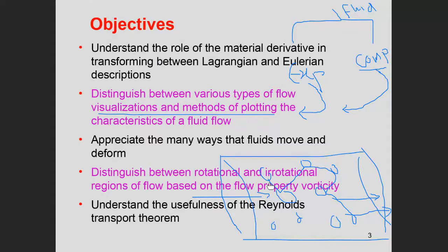Some people said, no, no, no. This Lagrangian approach, which conceives the flow as a huge number of particles, is not realistic, because statistically it is difficult to follow a huge number of particles. They said no, rather than a particle, they will look at ensembles. Ensembles means talking about a small computational domain. Do you see my drawing? A finite volume, yes?